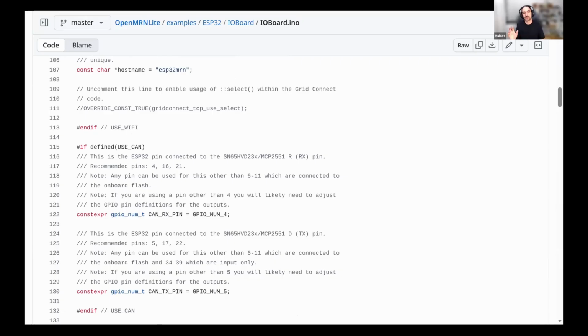All the CAN transceivers are almost always pin compatible, and in just very few extreme examples where you have like a 3 volt versus 5 volt trickiness, you have to be a little bit careful about it. But the fact that there is a CAN transceiver written here, it really doesn't matter because there are 100 CAN transceivers, and at least 85 of those 100 is going to work.